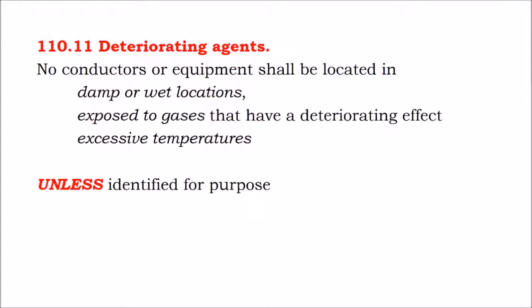If they're protected, if they're sheltered outdoors, if they're not subject to water spray on a regular basis like rainfall, that's not necessarily a wet location. That could be a damp location. You can have interior wet locations. A wet location is something that gets sprayed with water. So a car wash might be enclosed, but that would be an interior wet condition. Usually, a rooftop would also be a wet condition.